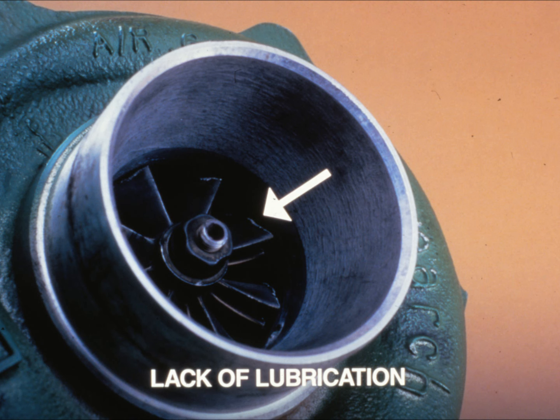Lack of lubrication is one of the main causes of turbocharger failure. The resulting damage to the bearings and shaft often causes wheel rub in the turbocharger. An adequate supply of clean lubricating oil is critical to performance. An engine problem that interrupts the oil supply can damage the turbocharger. Frequent engine shutdowns without a cool-down period can also damage the turbocharger. Placing the engine under load without proper warm-up can also cause damage.